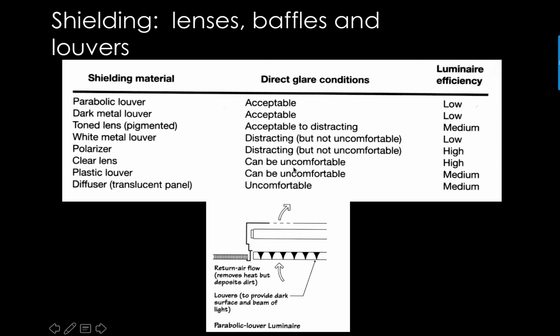The one thing you need to be aware of, and this is particularly true when you have something like a fluorescent fixture, is that you really do want to control that glare, but you do lose efficiency in the light fixture. What I think a lot of you might see if you are driving around is that New England has been replacing their street lights bit by bit with LED light sources. They are quite glary unless you live in a rich town. The unfortunate factor is that they just aren't using proper shielding on those fixtures. But one of the reasons I think they aren't is because of the reduced efficiency of the fixtures. Alas, I think that's a miscalculation.